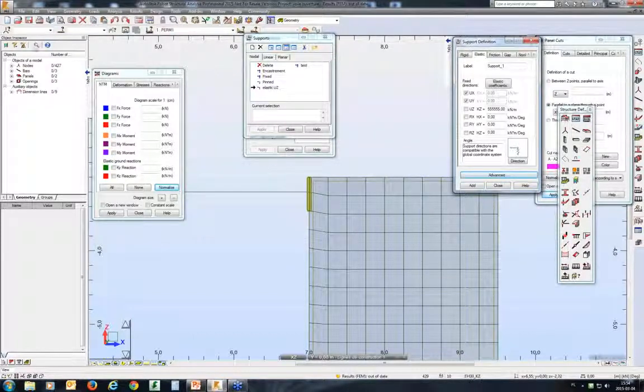Deleting isolated nodes only visible in the table: how can you make sure that it does not hurt your structure? And the answer: it may happen that some isolated nodes are not displayed on view, so delete them from the table. Another way is to open the file in repair mode and delete them if still existing.